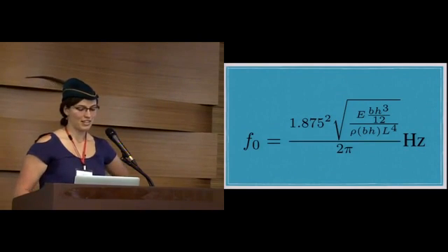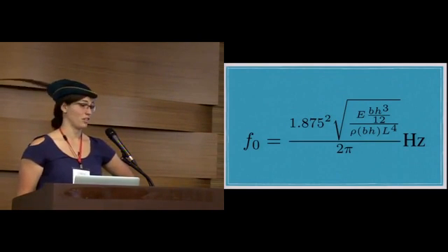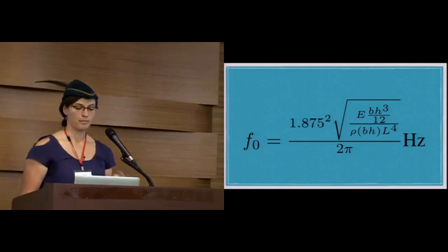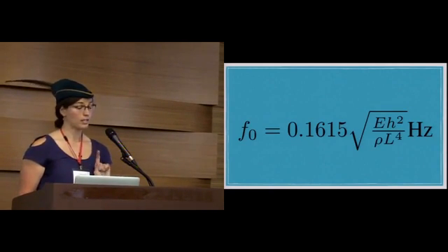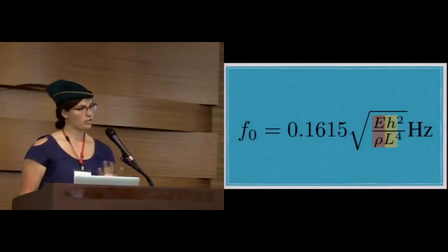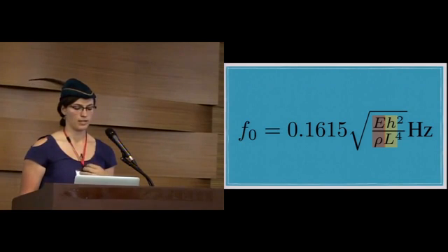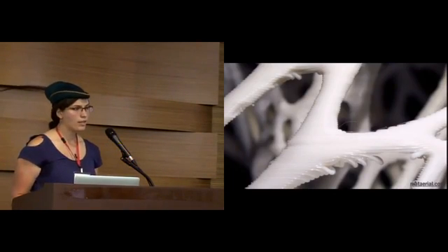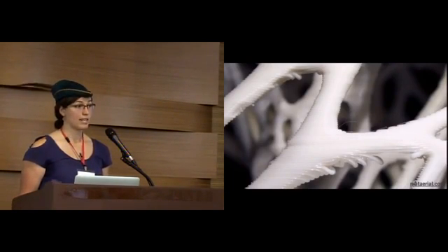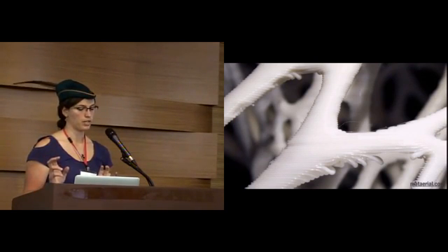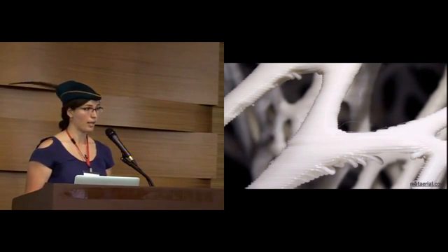So how exactly does a material affect the frequency? Luckily, mechanical engineering has studied the behavior of vibrational structures. They even provide us with a closed-form model of how a cantilever operates. So if we simplify this, we can clearly see our materials parameters and our model parameters coming into play. Interestingly, the breadth of the tine actually cancels out. There's one thing about the model we're using. It assumes a uniform cantilevered beam, so we weren't sure if it would hold when we use 3D printing. The way that objects are fabricated on 3D printers, they're not uniform, and each direction has a different structure.